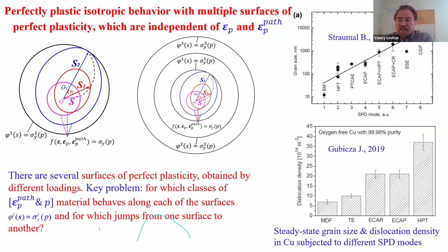So I cannot see that the pressure gradient in our range affects phase transformation. We also have a paper where we fit simulation and experimental results with pressure up to 400 GPa. There is, of course, a huge pressure gradient. I hoped that local theory would fail, and then I would need to develop a non-local theory of plasticity, so it would be fun for me. But surprisingly, everything was described properly with local theory. This was just plasticity, no phase transformation. So at the moment, I don't see a reason, for the cases we studied, to take the pressure gradient into account as a governing parameter for phase transformation. Maybe in shock loading this is more important, but in our case it's not.